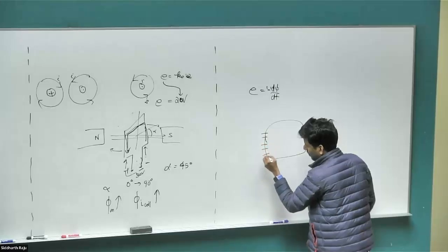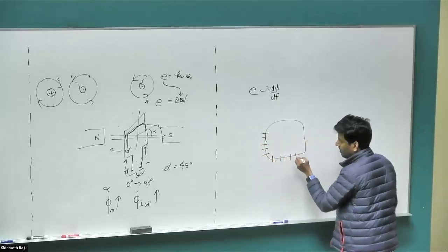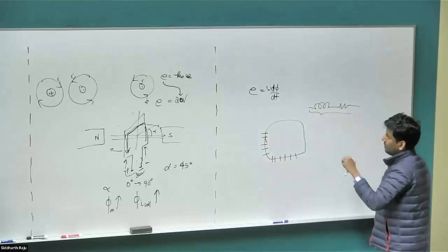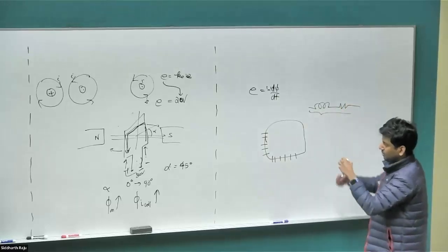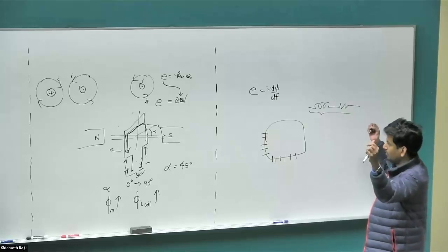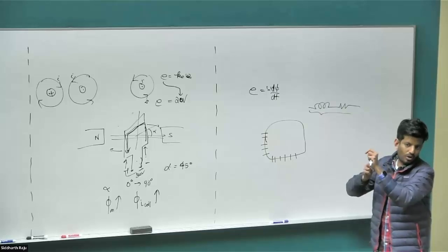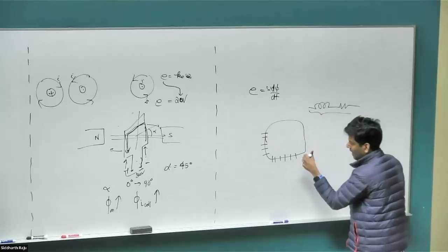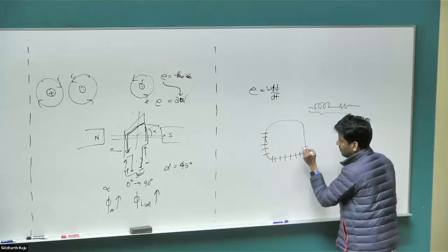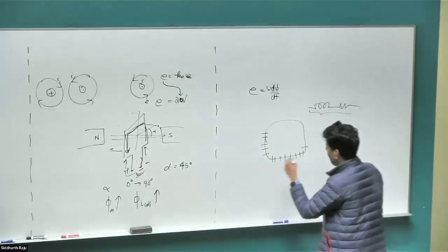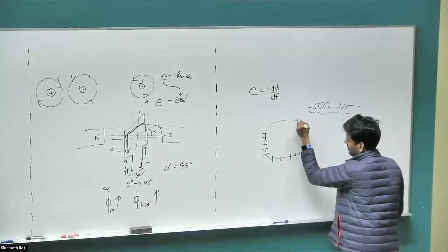So those of you who have done a power system course know that we do these clumped network models. When we have a transmission line, we put an inductance and resistance to represent hundreds of miles of transmission line. But in reality, it's tiny elements where the voltage is being dropped across the transmission line. Same thing happens here. The EMF is not developed at one single point and lost in a clumped way in some particular point. That's the way we draw it to simplify our analysis.